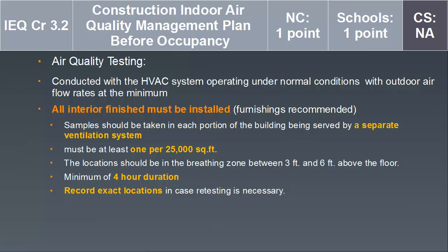For air quality testing option, this is conducted with the HVAC system operating under normal conditions with outdoor airflow rates at the minimum. So really you're testing the worst case scenario. Similar to the flush out, all interior finishes must be installed, furnishings as well if possible. It's important to memorize this criteria.